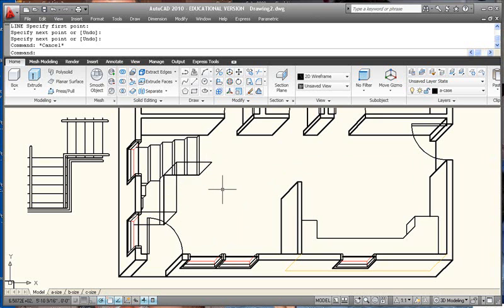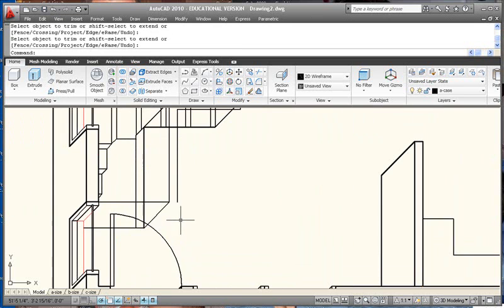obviously put posts in there, or if we want to make this a wall with a cap or just a regular wall that's a half-height wall, we could draw a line across from here 4 inches and let's just have that go to here. Just offset that line 4 inches and trim. So we're drawing the upper edge of the wall here and then just connecting the dots.